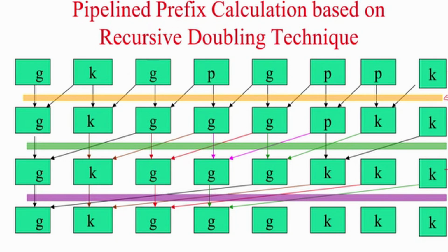So, the register basically gets updated only when there is a clock pulse. The first set of data gets processed and stored here, then the second stage will start working on the first result. Now, the second set of data can be processed by stage 1, while the first set of data is processed by stage 2. The processing that happens here will not change the inputs to the second stage, because I have registers here and the registers will not change until they see a clock pulse.